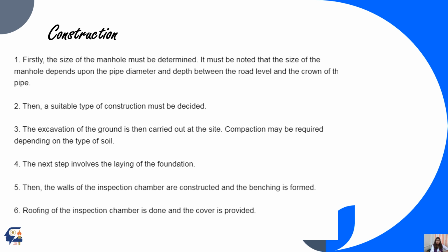Next step involves the laying of the foundation. Then later the walls of the inspection chambers are constructed and benching is formed. Roofing of the inspection chamber is done and the cover is provided.